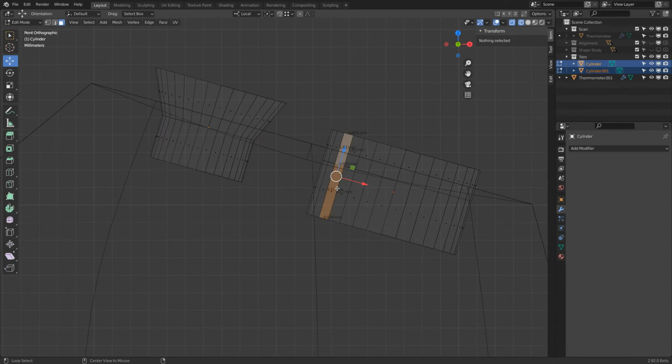And then I can basically select the top ring and sink it down a little bit more. And there you can see here how I will get a chamfered edge. And then there too. Okay, very nice. Edge length we can turn off. We go to object mode, turn this off, go to here, turn this back on, and there. Sweet. Okay, and there you can see this chamfered edge.